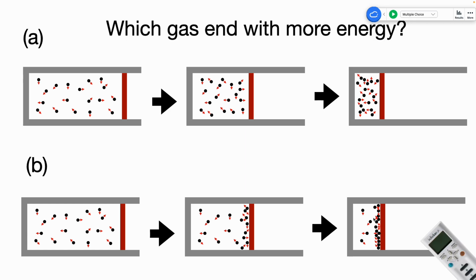These processes are different, and the reason we call them different names is because of their physical consequences. If you compare pushing a piston really fast and slowly, which one requires more energy? Does it take more energy to compress it really fast or slowly? Your total displacement is the same. Work is force times displacement. You are doing the same amount of displacement, so that's not what you should consider. What you should consider is how the accumulation affects the pressure on the piston.